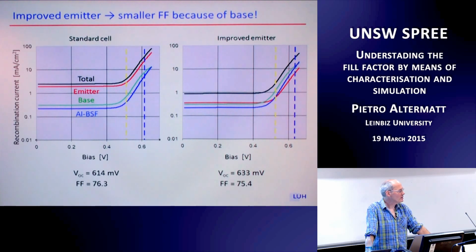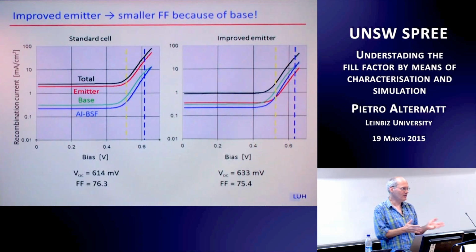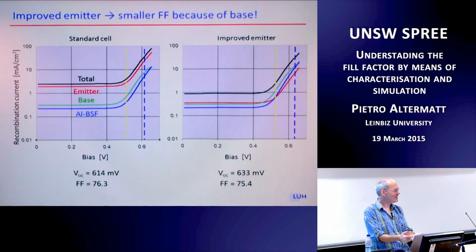You would actually notice just by normal IV curve analysis I showed you at the beginning. If you do that quite systematically, like at the beginning, with IV curve analysis, you notice that without any simulations. But I show you here the simulations because the dynamics, in a way, becomes apparent. So it's the ideality factor that causes the low fill factor.